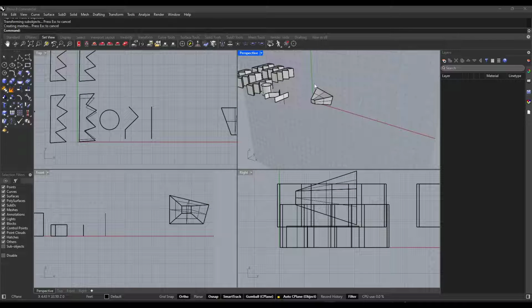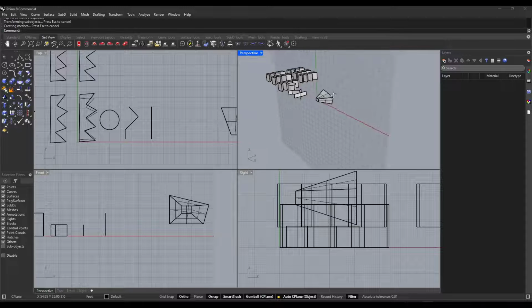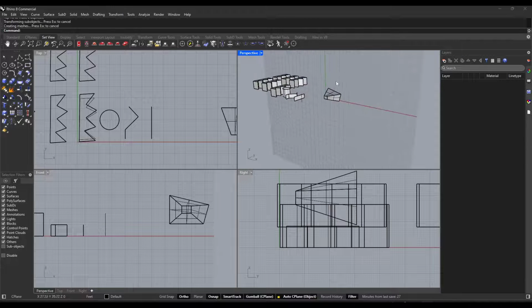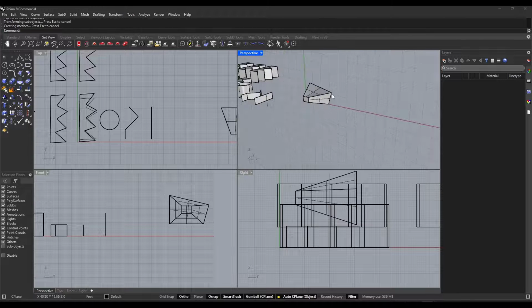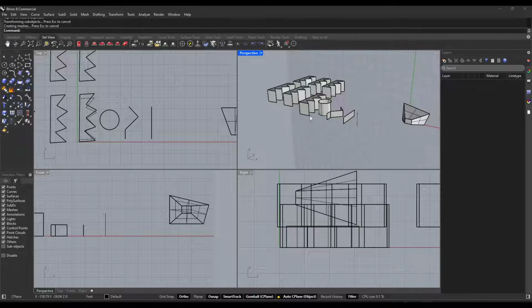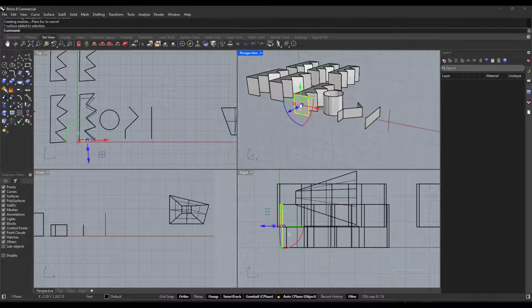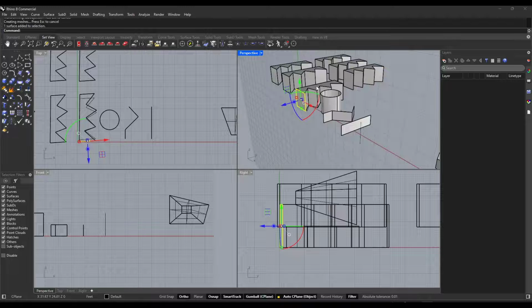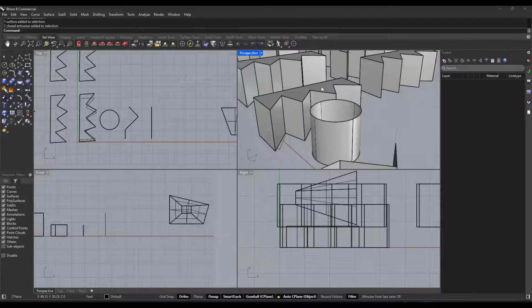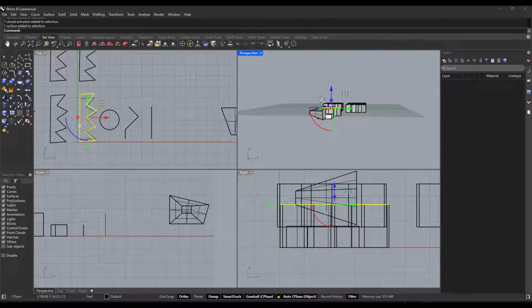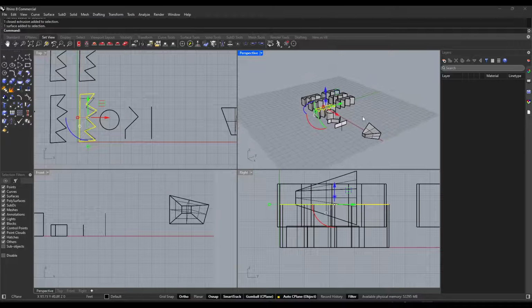And so one thing you might notice happened when we did that is the construction plane, or this three-dimensional plane that's in here, changed when we clicked on this face. That's because there's an option in here for auto C-plane. What that means is that when we do something like clicking on an individual object like this, that construction plane in our 3D space is going to automatically align with whatever we have selected in here.